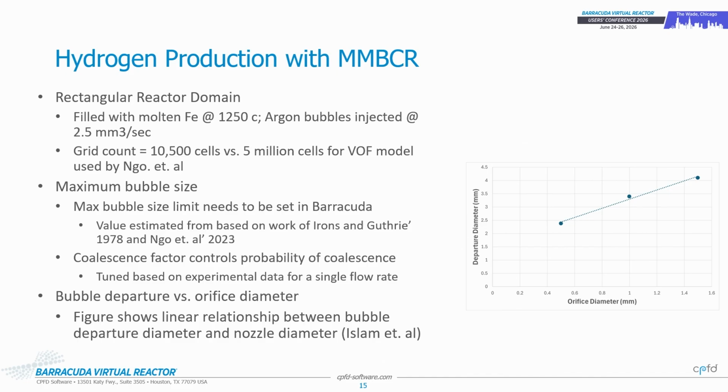If you have an in-house CFD tool with VOF, you can run one single simulation at a given flow rate, figure out what the max bubble size is, and then carry it into your subsequent simulations.